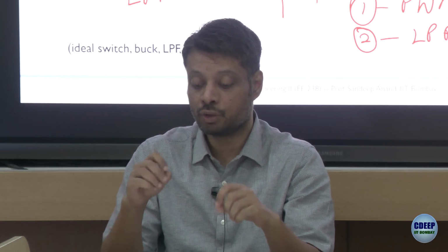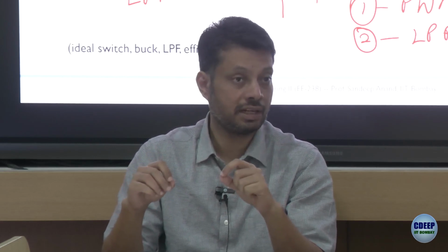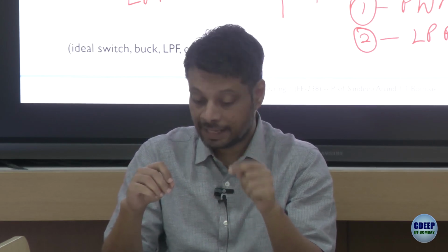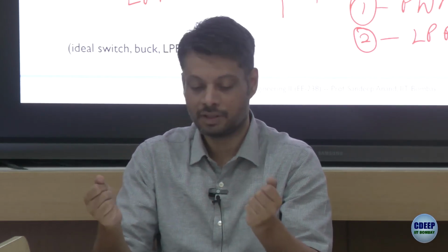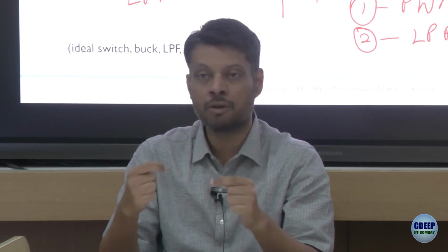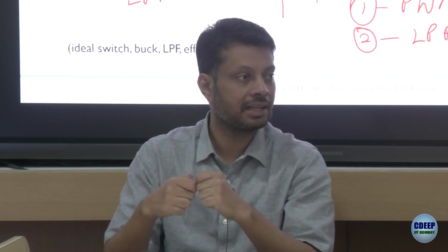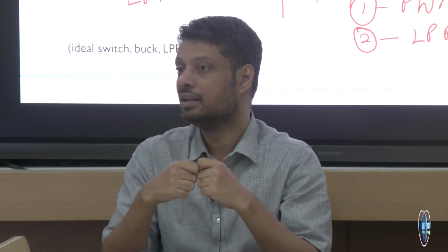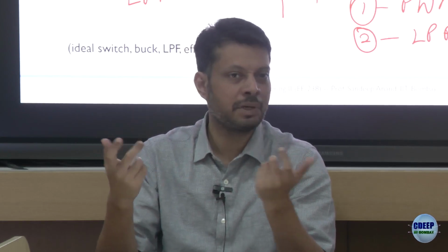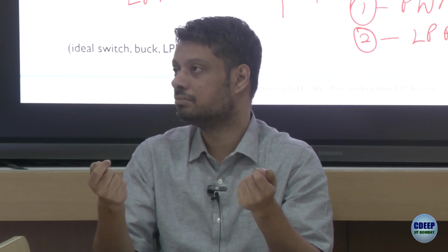For this, what you require is a switch, S1, S2, and an inductor and a capacitor. By now, we have been talking about inductors and capacitors for quite some time, and you know these exist and you have seen them. The switches S1 and S2 cannot be mechanical switches, because a mechanical switch takes finite time to close and open, anything between a few seconds in the best case, maybe half a second.